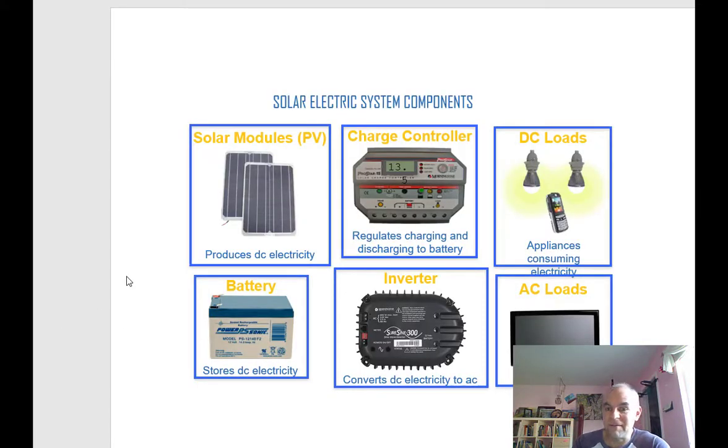And then in most solar systems, you have solar power, and you have to have something that is charging the battery. You can tie a solar panel directly to a battery and charge the battery that way. But this charge controller is kind of like the smarts behind a solar system. A solar system being a system of solar panels and batteries and things that you want to have that power. This knows when the battery is low, and it tells the solar panel to supply the battery with current. So this thing provides some smarts.